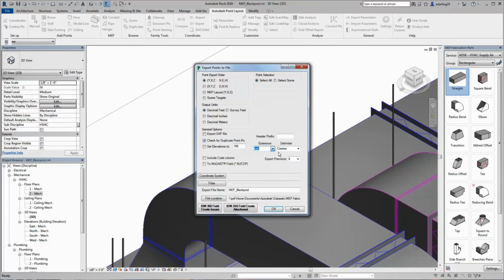As I mentioned earlier, these services content is the same as used in Revit. You remember the service configuration in Revit, the same options, the same content. So you can directly choose your library, what type of duct you are going to use, and start creating it inside CADmep. You can create your branches, left run or right run. You can see it automatically adds fittings and everything, all types of transitions and elbows.